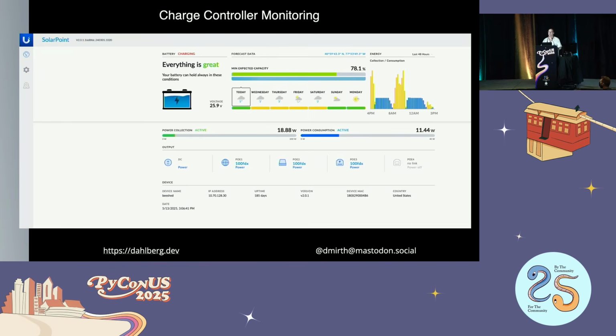Monitoring of the equipment is crucial. Any and all components can and will fail. The batteries will run out of a charge, the charge controller will fail and stop providing power from the solar panel to the batteries, and the RPI will get fried because you forgot to put a fuse in line. If you spend time setting it up, spend a little more putting in some method of monitoring it.